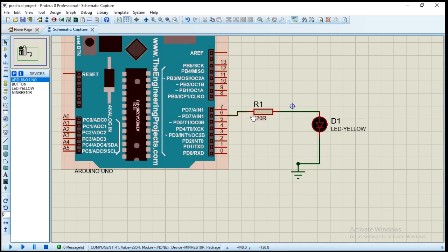So you can see where I connected it. This is our LED on pin 6. We want to get a varying voltage, unlike digitalWrite where we have only high or low. So we want to vary the voltage, which means we want to control the brightness of this LED. Whenever we have a varying voltage, the brightness of this LED depends on the voltage we feed to it. So let's see what analogWrite is all about.